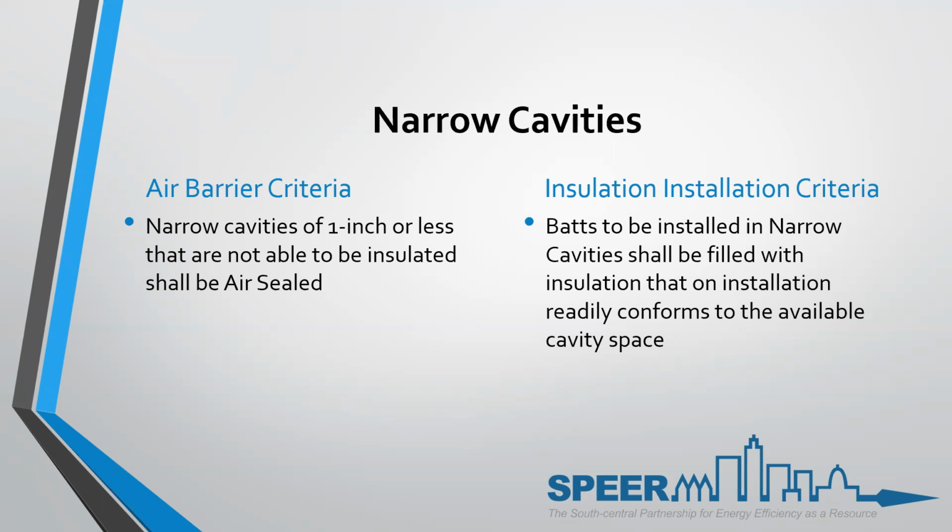When you take a 14.5-inch batt and cram it into a 6-inch opening, you've made more of a solid than you do an air permeable insulation out of it. So the resistance to heat transfer is reduced. So it should never be just crushed and crammed in there. It should be cut to fit.